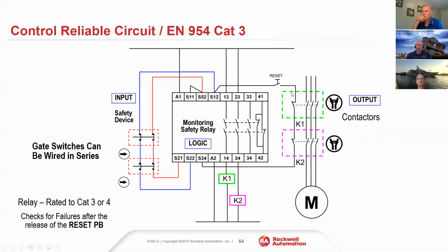But the principle of the monitoring is the same. We have our normally closed contact here, which is only closed when our normally open poles are actually open. So if we had an issue where one of these contactors failed, the second contactor would open. The safety system would be implemented, the motor would stop, and when we went to reset the circuit, this pole up here would be open in our reset string, so we would not be able to reset the circuit without correcting that issue. Over here in the situation with an input, let's say we welded one of these contacts, or somehow it was damaged and was not physically opening, then the second contact would open.